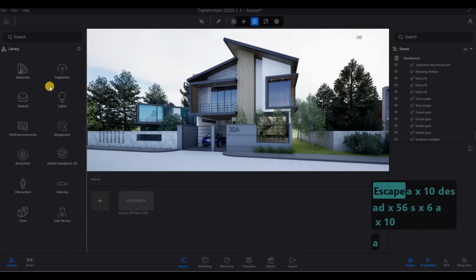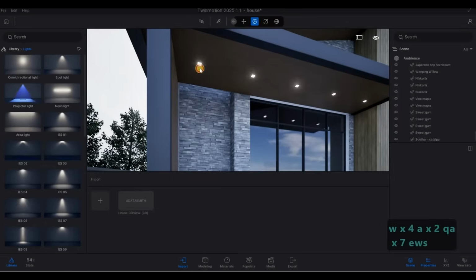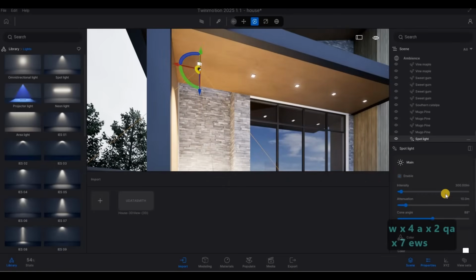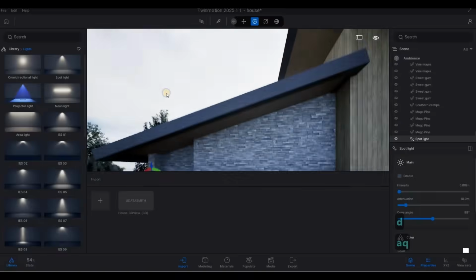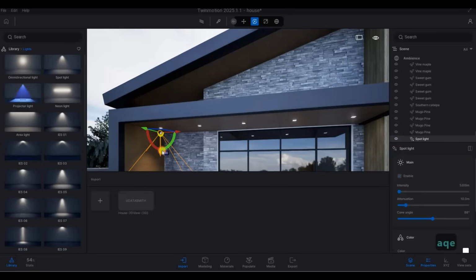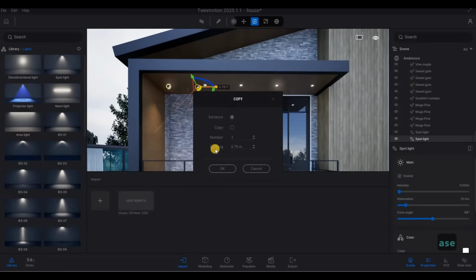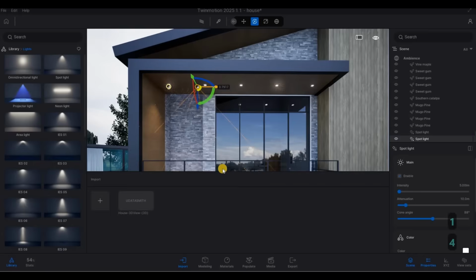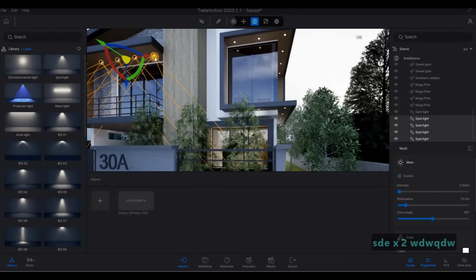And then now what we can do is add in lights, and we're gonna put in spotlight, and in terms of intensity, we could do 5. And then because we know the distancing, we just need to count how many more. So 4 more with 1 meter or 1000 millimeters, and then 4 more. And then here as well.